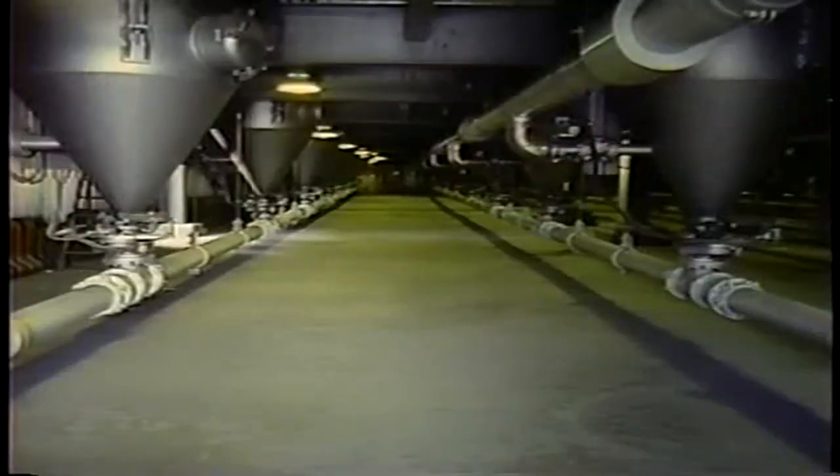A tube leak can also affect a boiler's ability to handle fly ash. Dry fly ash moves out of a boiler along with the air and flue gas on the way to the stack. Between the boiler and the stack, a fly ash handling system separates the fly ash from the flue gas. However, if steam or water from a leaking tube is sprayed into the gas flow path, it will turn the dry powdery ash into mud, causing it to stick to boiler tubes.